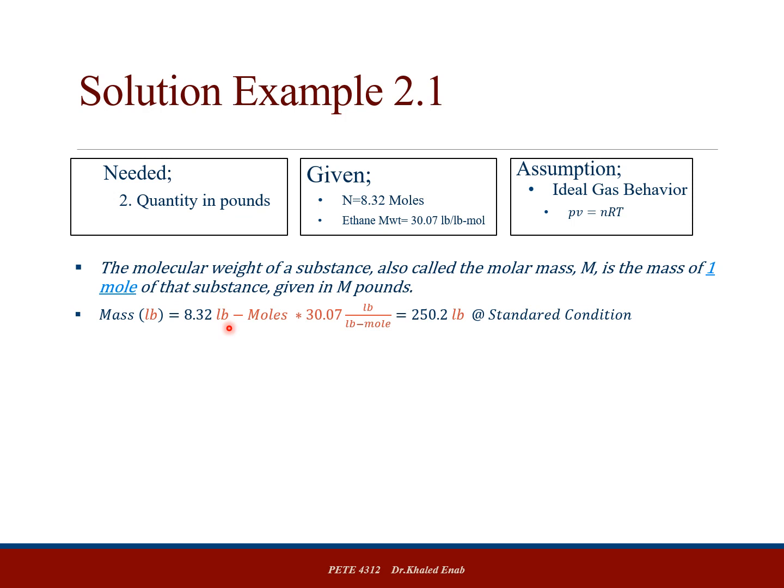And I tell you that the quantity in this tank is 8.32 pound moles. When you release the pressure and the temperature to go to 14.7 and 60, the volume will change, right? Definitely the volume will change. But will the pound moles change? Will the mass change? Is the mass a function of pressure and temperature? No. Mass is not a function of pressure and temperature. Mass is a function of the number of moles, right?